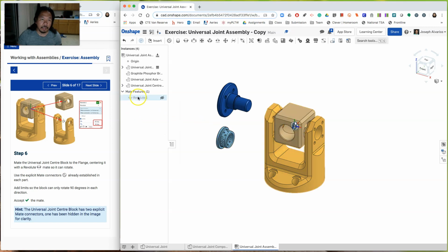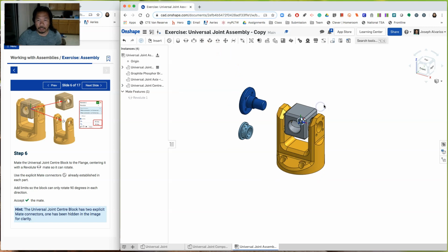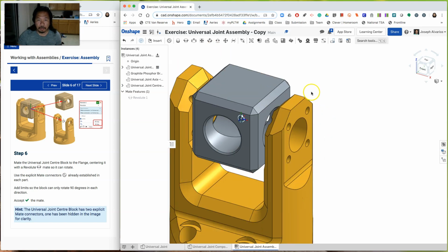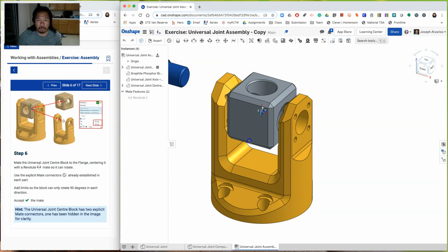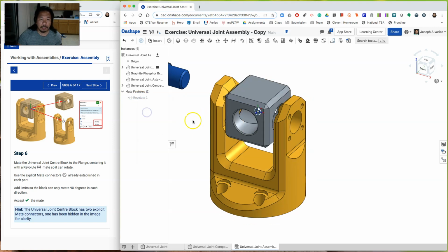So now it's reset, but we have to limit its movement. So right click, click on edit, and then click on limits and say -90 here, and right here would be 90. Okay, click check. Let's see what it does now. So it does this, 1, and then it does the opposite direction, 2. Okay, so right click on revolute and then say reset.